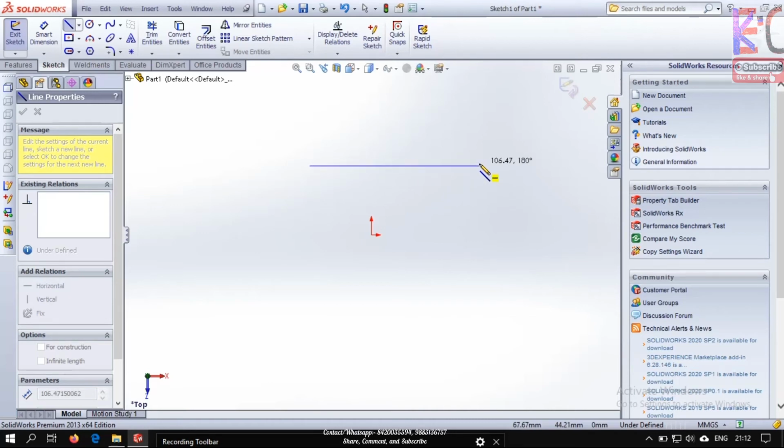You can see there's a yellow minus sign. This means it's horizontal. If I go over here, you can see the minus gets inverted 90 degrees. That means it's a vertical straight line. If I change it like this, or like this, it will not show anything. But if I bring it over here, you can understand they are showing some relations.